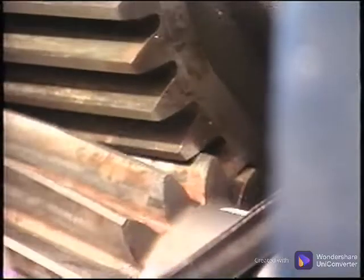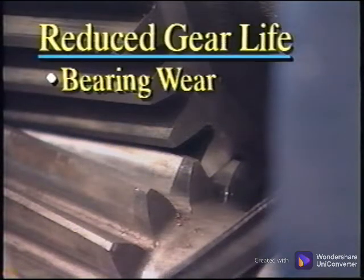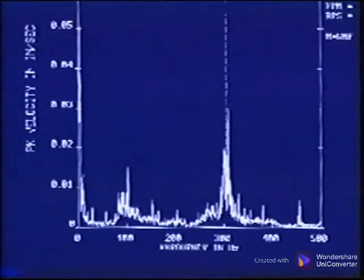A good set of gears with proper tolerances that conform to the standards set by AGMA, American Gear Manufacturers Association, should last 20 years or more. However, bearing wear, excessive loading, and imperfections in the machining and material of the parts can cause the in-service life to be reduced substantially. This spectrum is from the drive side of a paper machine.